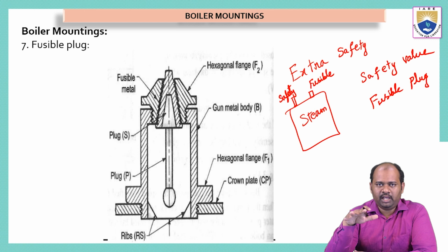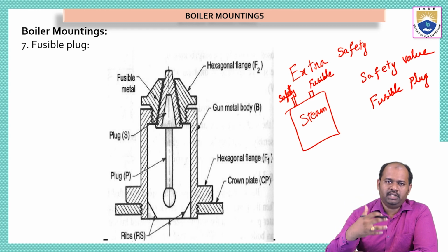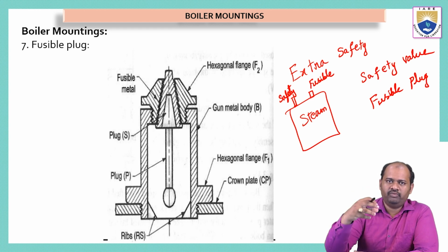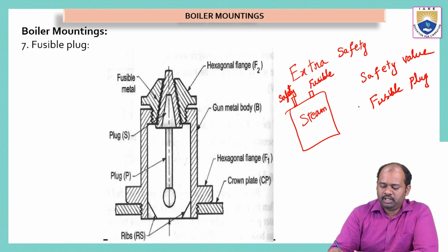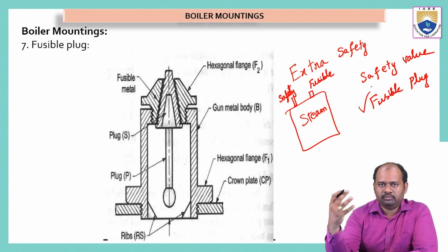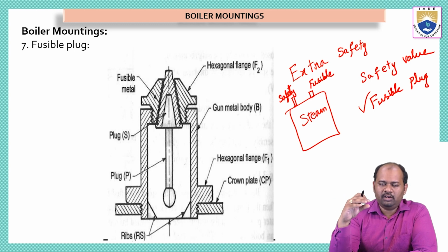Now on the surface of the cap of the pressure cooker we have another valve. This is for extra safety. So when this safety valve does not work, or if any food particle blocks the safety valve, the pressure cannot be released through the whistle. Then this fusible plug will blow off. It is made up of a thin layer of gunmetal or aluminium. This metal will blow off, that means it will be burnt out, due to the pressure inside the pressure cooker, and the steam will be released